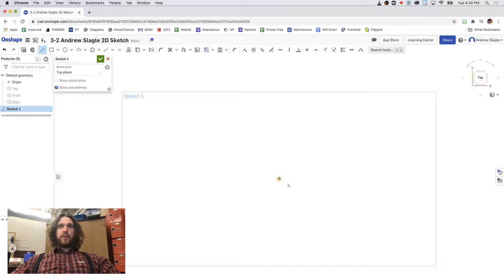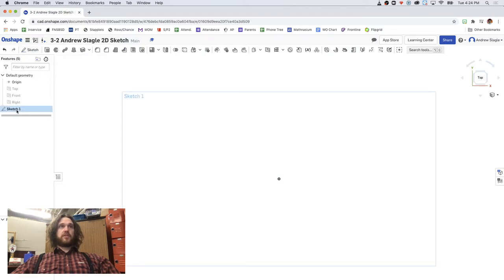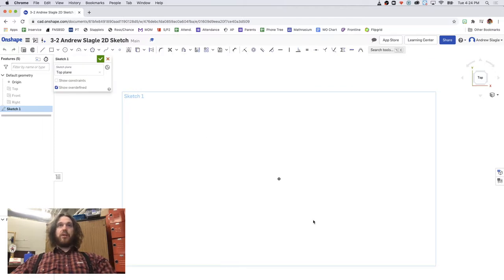If that bottom line is 70 inches and I want this to be centered, I'm going to keep this horizontal and go out. Oh, you know what? First thing, those are likely in millimeters. So before I get started, I'm going to come up here and change my workspace units to millimeters. I should have started with that. That pulled me out of my sketch, so I've got to go back into my sketch, press L to grab my line tool quickly, and then I can draw. Remember, that was a 70 millimeter line coming across there. So let's go ahead and go out 35 to the right.